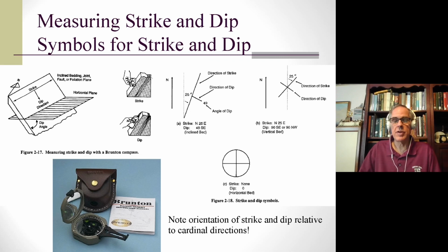Now, in mentioning this, and I'm going to have some other material elsewhere on the topic, you have two things. The dip you see there is 90 degrees out from the strike, and that's the true dip. That's the maximum down. However, we also have something called the apparent dip, which is the angle from the intersection of the strike line, other than the perpendicular from the strike line.